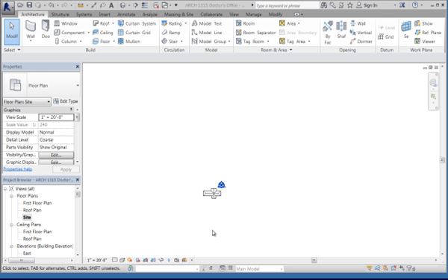There's another site plan over here on the next page. And you can see that on page 119, where it says drawing scale, the site plan should be drawn to the most appropriate scale. For example, 1 inch equals 10 feet or 1 inch equals 20 feet. 1/4 inch will be way too big. Most of you had to put your buildings at what, 3/32 or something? So you're probably going to be 1 inch equals 20 feet.